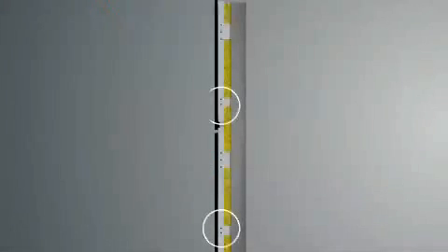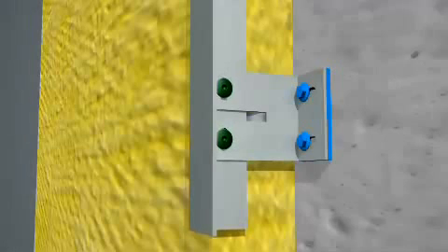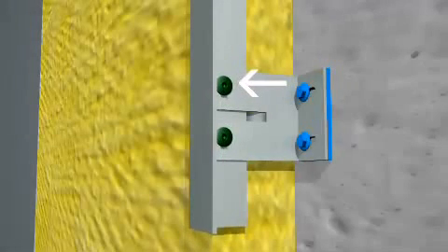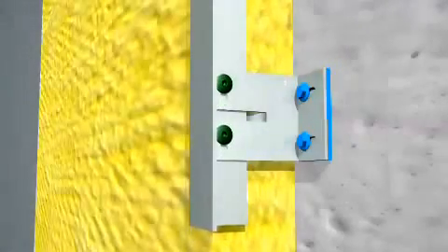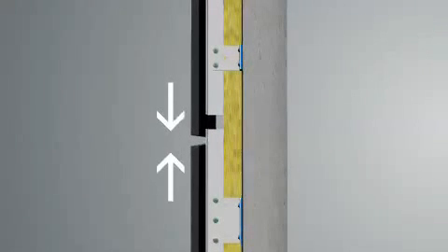The other wall brackets, which are smaller, are the gliding points. The rivet or screw in these is inserted into the elongated holes. This holds the profiles in place while still allowing them to move freely up and down to accommodate the thermal expansion of the aluminium. It is important to always leave a 20mm gap between the ends of the vertical profiles. This must coincide with a horizontal joint between the panels.